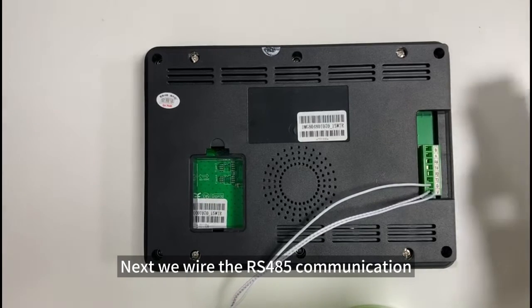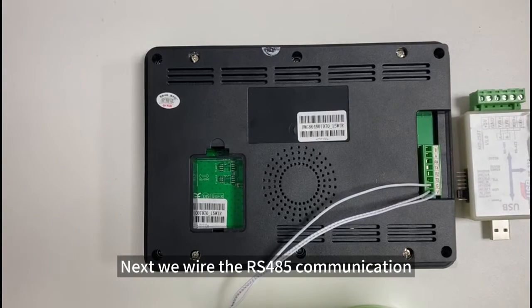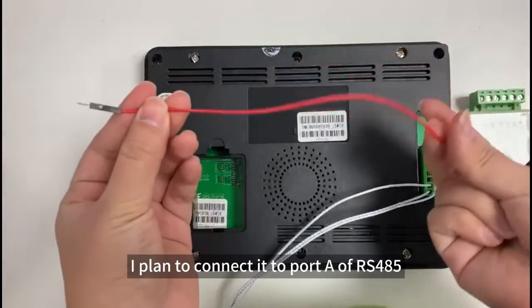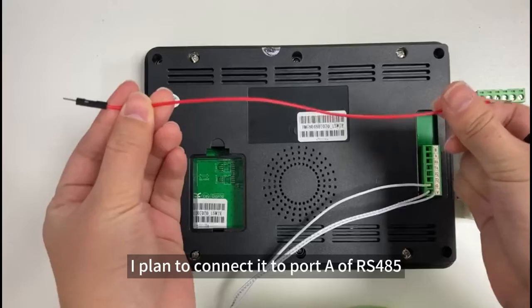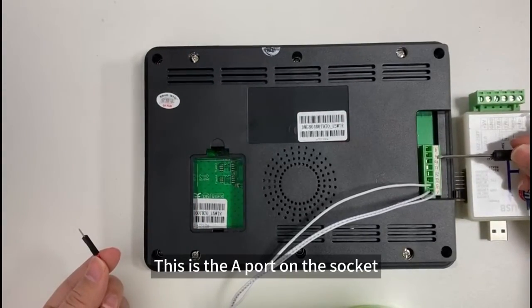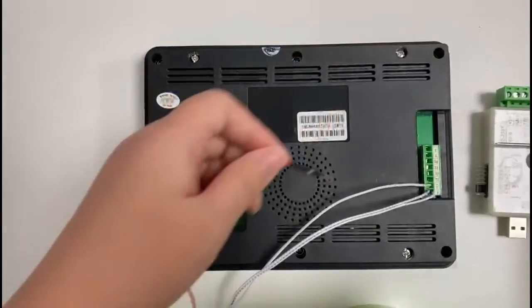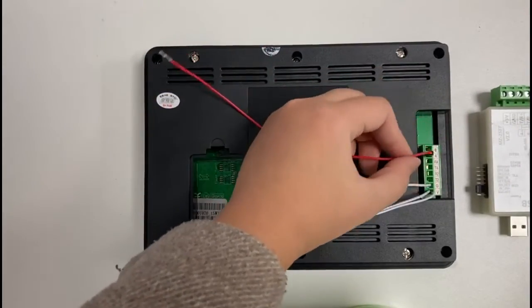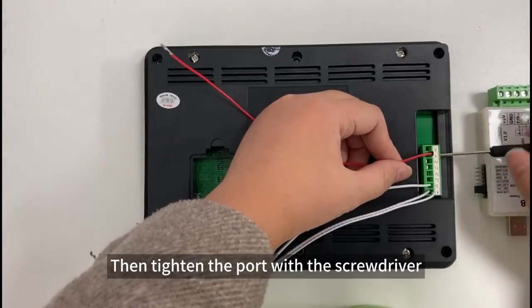Next we wire the RS485 communication. This is a red DuPont wire. I plan to connect it to port A of RS485. This is the A port on the socket. Connect the red DuPont wire to port A. Then tighten the port with the screwdriver.